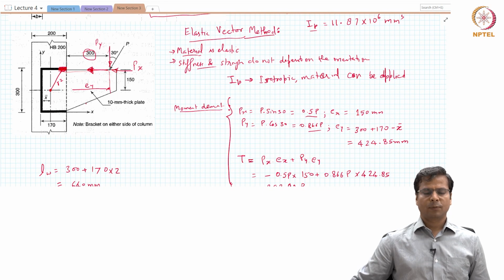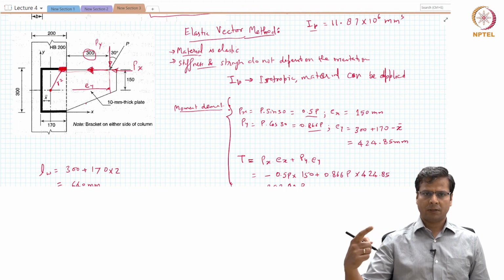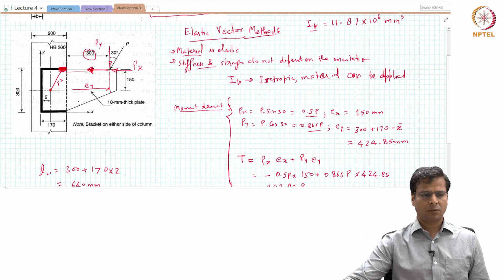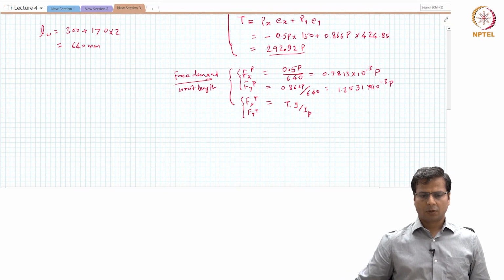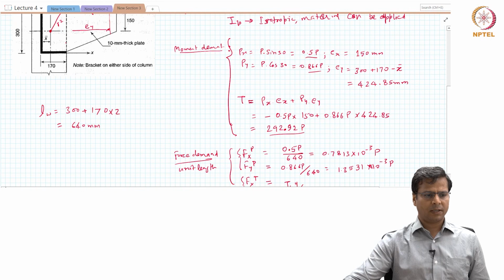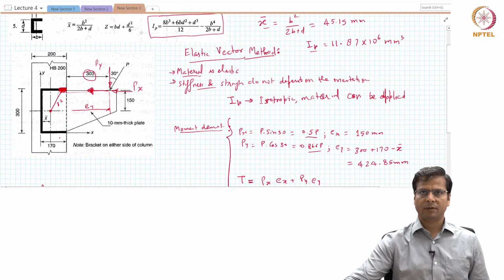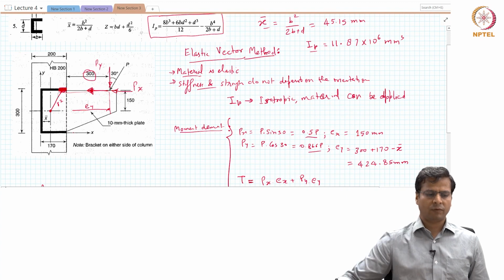The reason for that is, first, the force for a given rotation in that segment will be proportional to the distance, right? And in addition to that, the moment because of that force will again be proportional to the distance. So because of that, this distance comes twice in the equation. So now for each segment the force value will be different, that is the force that it applies to resist the moment. So which segment should we look at?